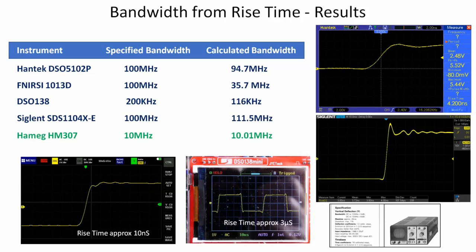And I've put that in green there because that isn't a measurement, that's just a calculation taken from the specification. But I think that lends hopefully a little bit more credibility to the 2 nanosecond rise time that Alan Wolke suggests is what we're getting from the Schmitt trigger. And of course, all of this is based on that 2 nanoseconds. That's not something I can actually measure, I'm afraid. However, I think those results speak for themselves.